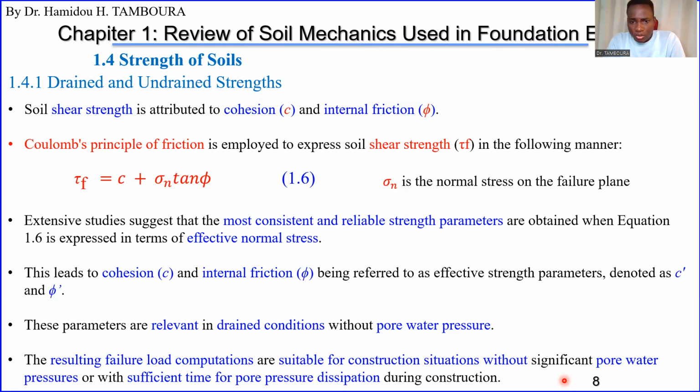Okay, water is escaping because water is incompressible. We cannot compress water. Okay, means we cannot reduce the volume of water. So the voids in the soil, if those voids are filled with water, if you load on that soil, the water will try to escape. So if you leave that load for a long time, or if your construction will take a long time, then the water will have time to escape but slowly. That's the meaning.